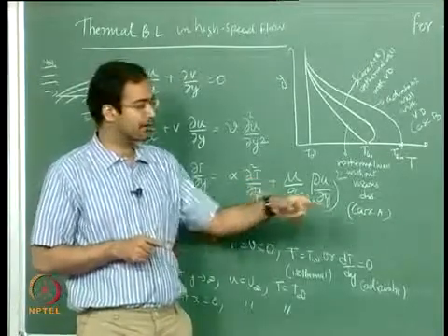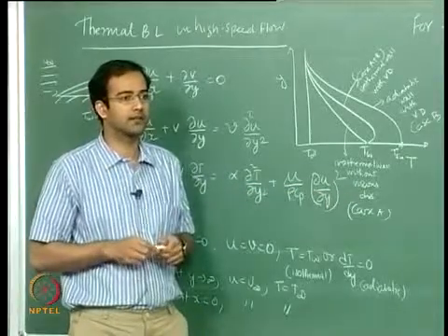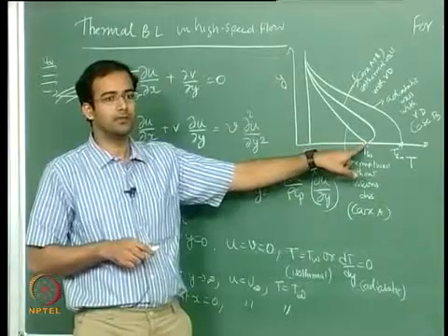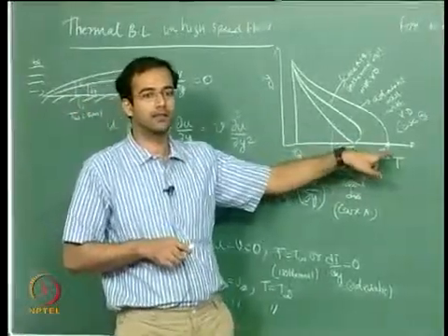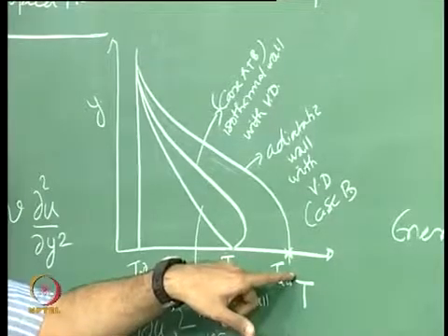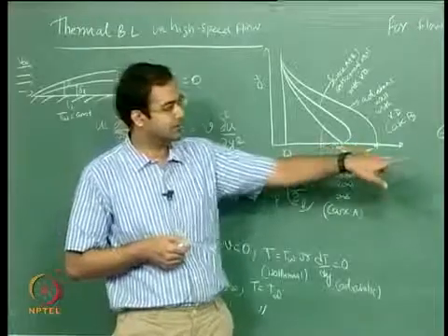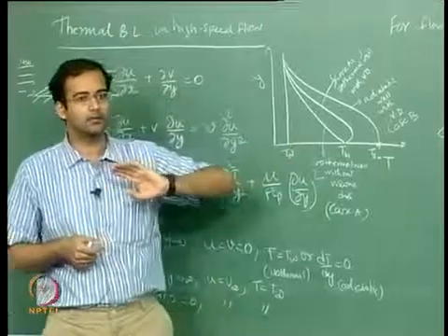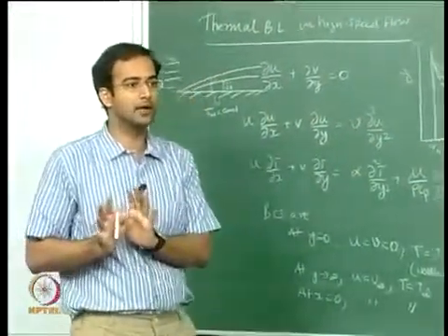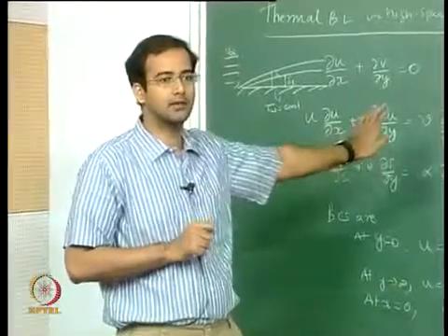Although we could have directly solved this and got the temperature profile, which is nothing but this which I have drawn here, we are also interested in calculating the adiabatic temperature. So in order to do that we have to solve case B. Now it's also possible that you can solve case A and case B separately and keep them, and you can linearly combine and get the solution for this generic problem.